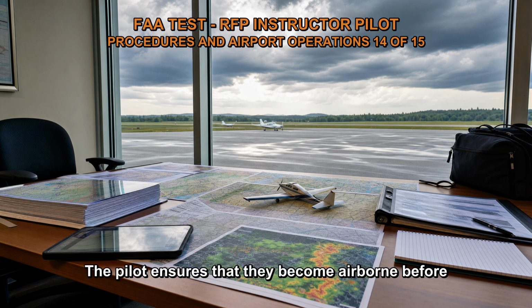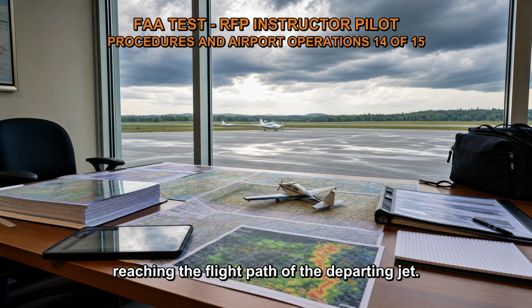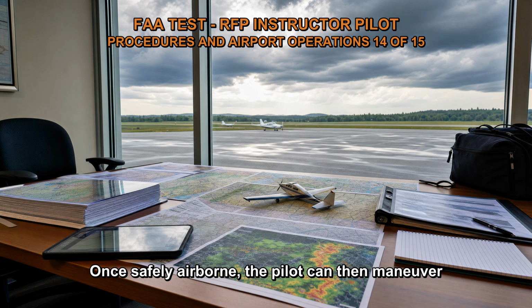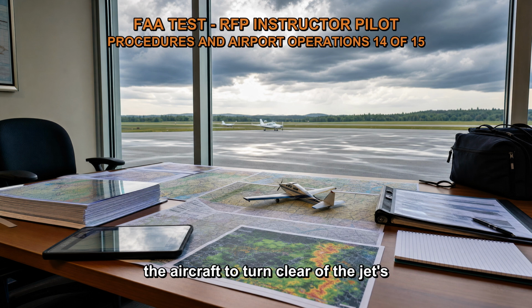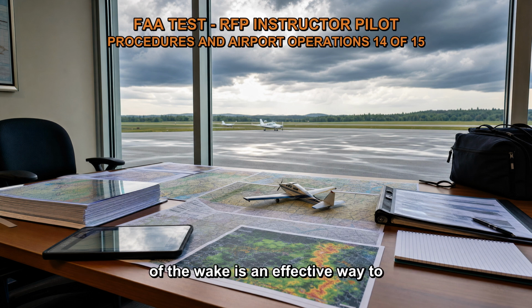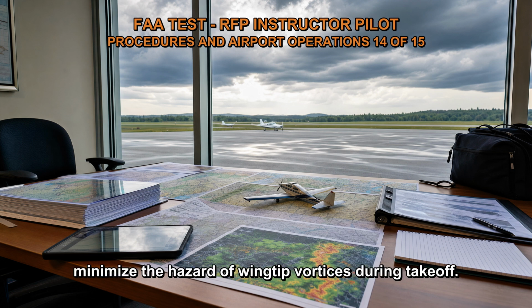The pilot ensures that they become airborne before reaching the flight path of the departing jet. Being airborne prior to reaching the jet's flight path allows the pilot's aircraft to climb above and away from the wake turbulence generated by the jet's wingtip vortices. Once safely airborne, the pilot can then maneuver the aircraft to turn clear of the jet's wake and avoid flying directly through it. This technique of becoming airborne and turning clear of the wake is an effective way to minimize the hazard of wingtip vortices during takeoff.